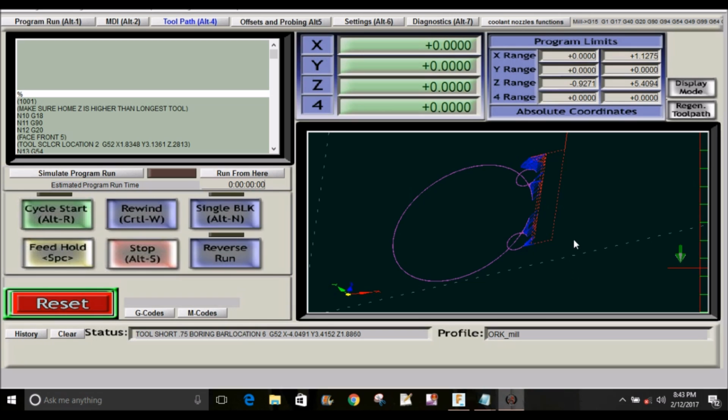Okay, I just wanted to show an example of how the code is displayed in Mach 3. The circular moves are always, for some reason, displayed this way, just giant crop circles. I don't know if it's a bug or I have a setting wrong in Mach 3, but it does cut on the correct toolpath, so I just sort of ignore this. I suggest cutting some air, and it'll cut the way it normally would. So this is just a display malfunction. I just wanted to show that if anybody sees it, the toolpaths are correct. It's just the display is wrong.